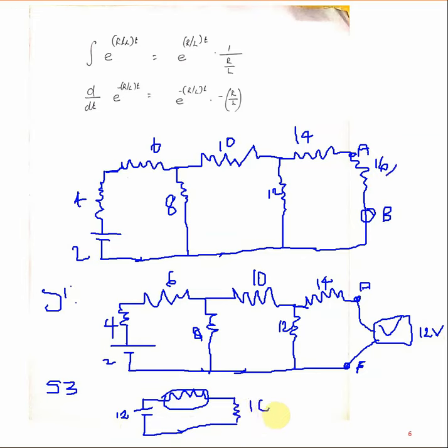Then in the circuit I want to measure the current, so one ammeter is connected here, that's all. One ammeter connected in series measures the current directly. That is the load current. So this is what to do practically for that theorem. This is a sample, and similarly you will do the remaining theorems the same way. You need to know how to connect the voltmeter and the ammeter.